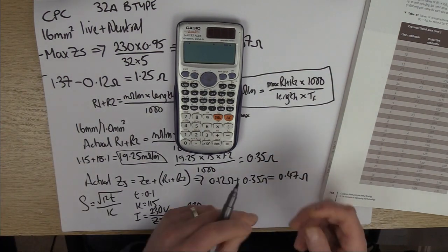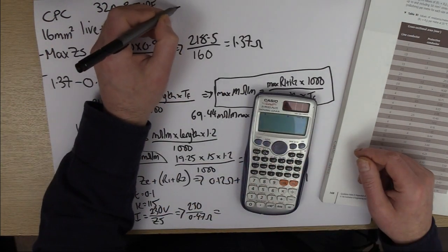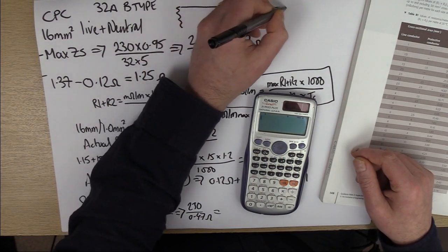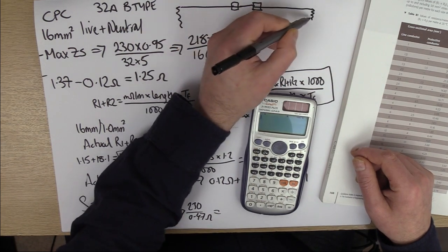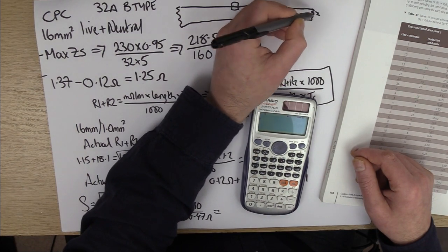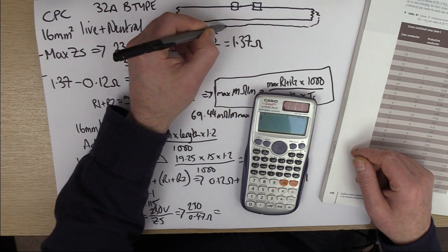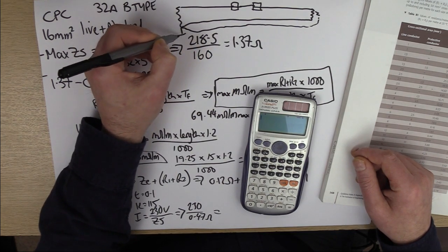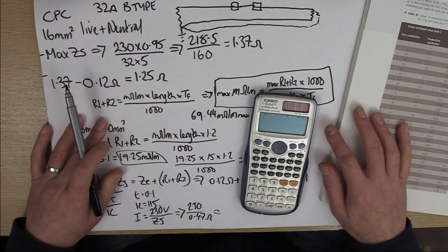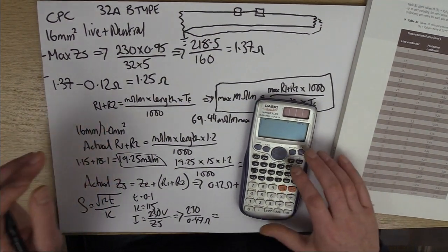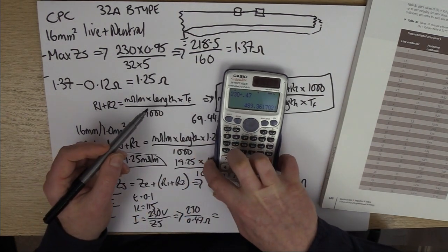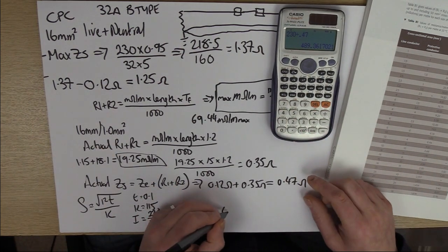So this is right at the end of the circuit, you know, substation, DNO's cut out, breaker. Right at the end of the circuit, got our heater load, neutral coming back, then our CPC is connected onto that. Let's say we got TNS. What we're saying is if the live touches the earth, this is how much fault current is going to flow. And it's telling us 489.4 amps.